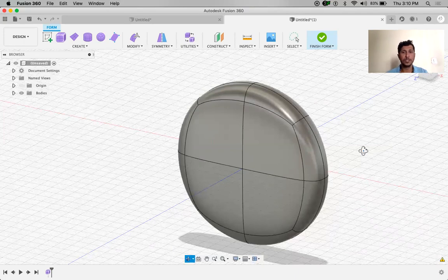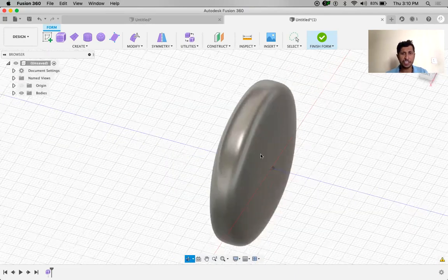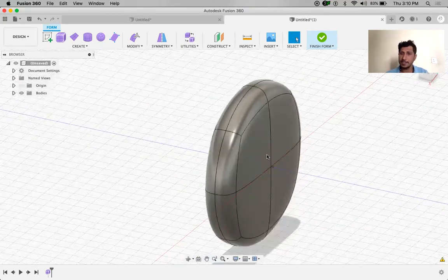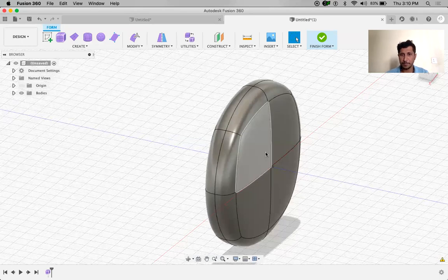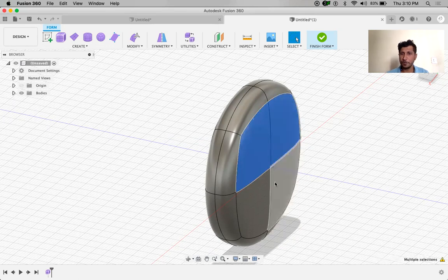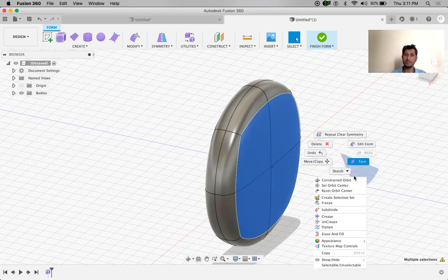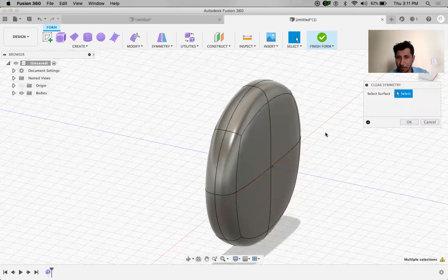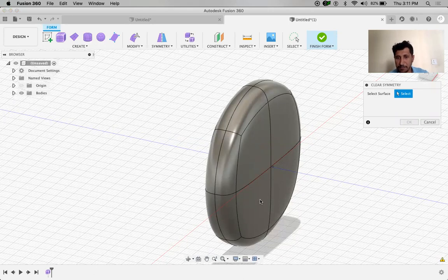Okay. So the next step, adding additional thickness here so that I can insert the speaker. So to add additional thickness, I can select all these four faces and I can just stretch it out. But the problem is it becomes a huge cylinder only. So what I want to do, first I want to reduce this face scale. Okay. After reducing the face scale, that only reduced portion I want to add thickness.